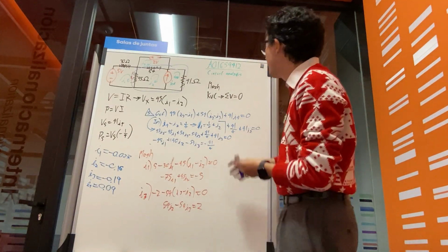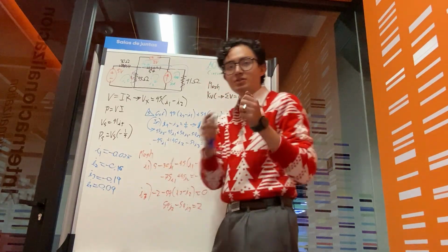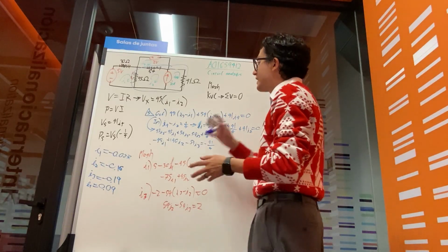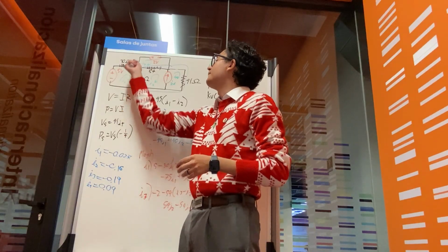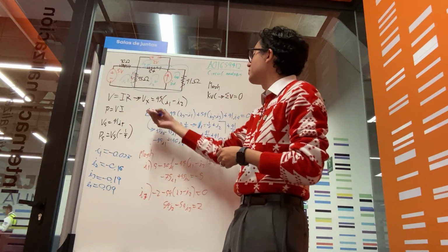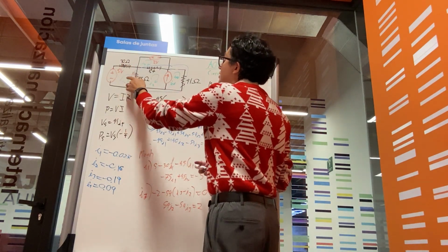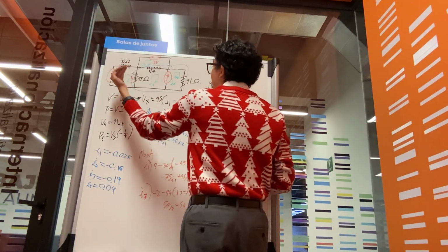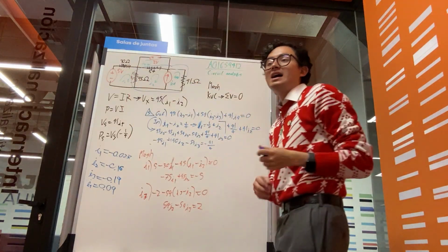Right now, I have already calculated. I just stated all of the equations, and I'm using the calculator. I solved the system of equations. It is very important to notice that, due to the polarity we're giving here, the outside of the super mesh will be positive, due to the minus-plus, since we're taking clockwise current. All of the outside will be positive.